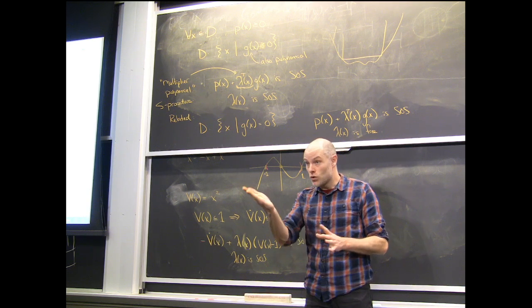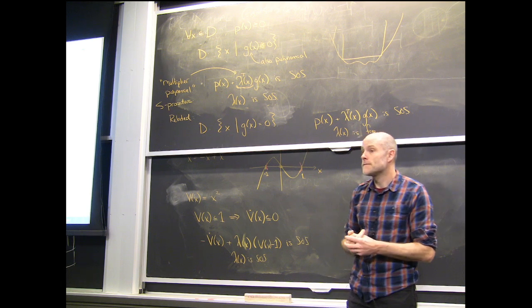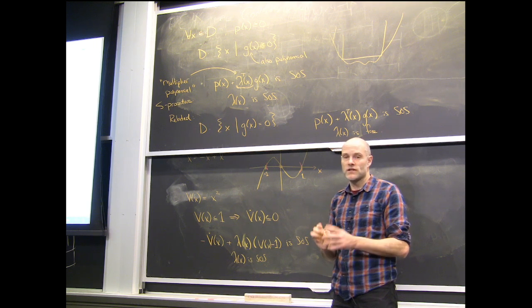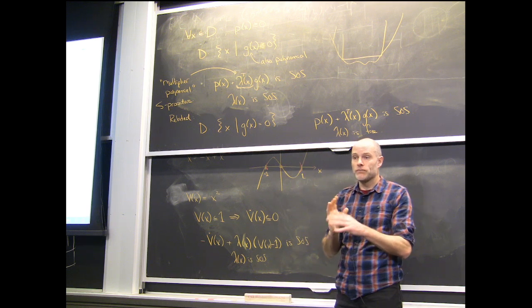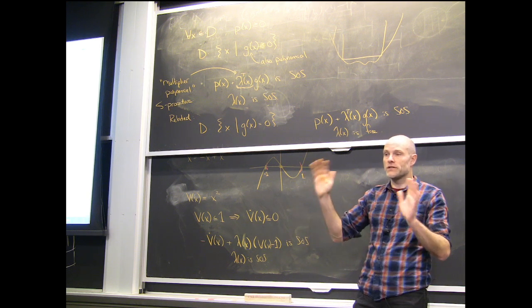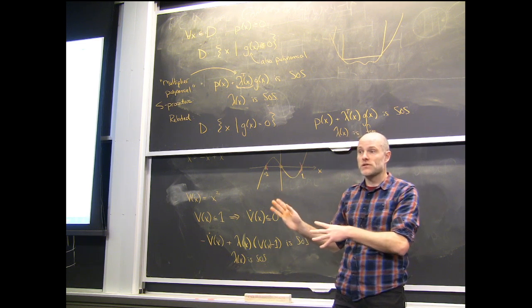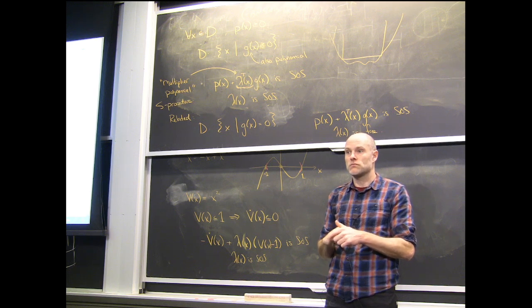If I didn't know, go ahead. But, for example, if you had two different Lyapunov functions, you could define an invariant set with one and then try to certify it with the other. That's true, you could. There are cases where you try to certify conditions over different regions, but to make a region of attraction analysis, you need it to be an invariant set. If you can get an invariant set some other way, you're welcome to.